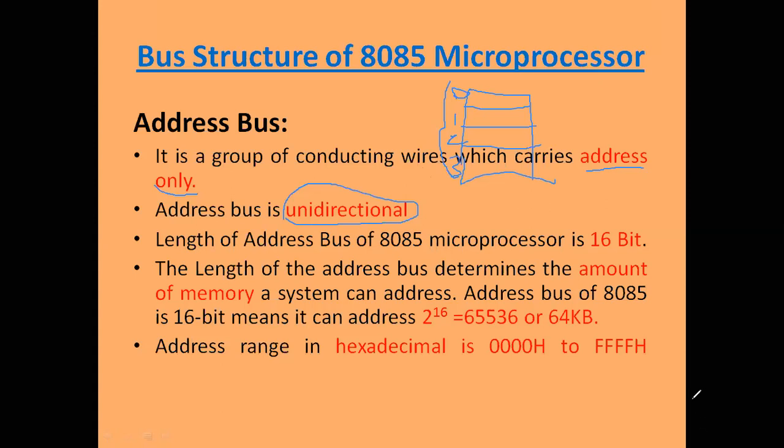When we need to transfer data, the transfer is done in 3 steps. First, the microprocessor will generate the address, meaning whose address it is from where the data transfer is to be done. Understood? For example, if input wants to send data, the input address should be generated by the microprocessor.